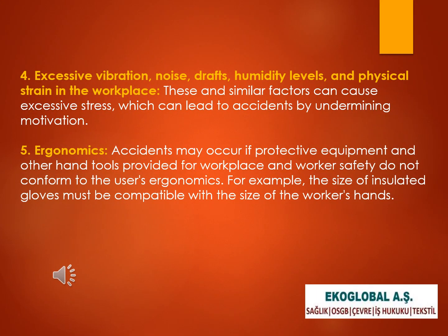Excessive vibration, noise, drafts, humidity levels, and physical strain in the workplace and similar factors can cause excessive stress, which can lead to accidents by undermining motivation. Accidents may occur if protective equipment and other hand tools provided for workplace and worker safety do not conform to the user's ergonomics. For example, the size of insulated gloves must be compatible with the size of the worker's hands.